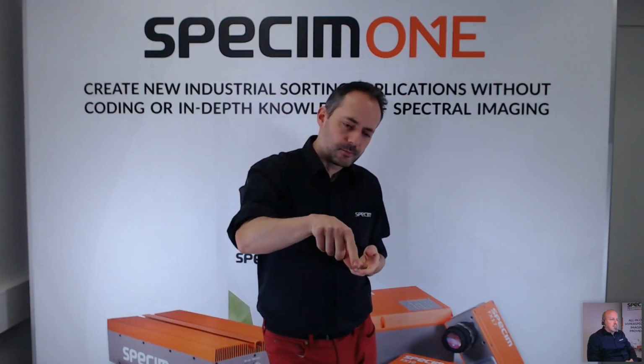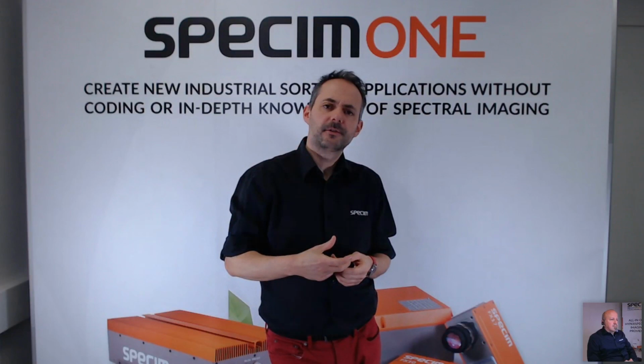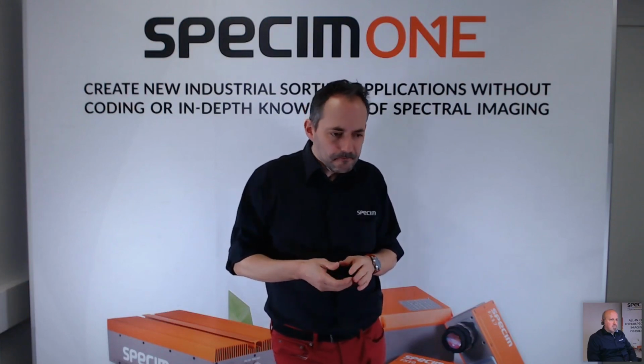Then normally those lasers are a point, they just have a point laser. But if you put some optics in front of it, for example, a Powell lens, you have the possibility to obtain a line. So this is actually what we got, and we tried. And here I have to say you get really a continuous signal of the full spectral range. And I remember when I was discussing with a person from NKT, he told us that the main application where they sell those is mostly for the separation of almonds and the shells. So that's what they say.